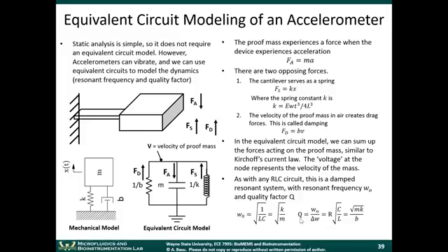When we make resonators for sensors, we want them to have a very high quality factor. We don't want energy losses in the system. The quality factor scales as the square root of M times K, divided by B. So you see the square root of M at the top. However, you also have the B at the bottom. When you make the devices small, the damping coefficients get smaller because there's less air resisting the movement of the mass. So you can still get very high quality factors at the microscale.